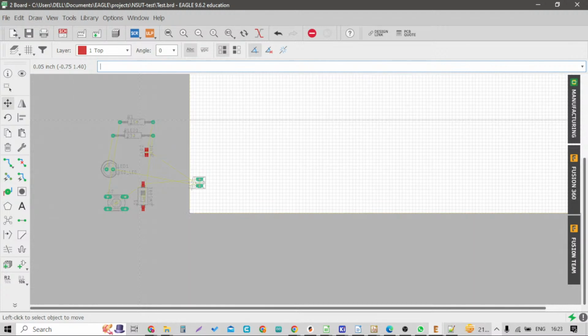So here in this design, we will be actually using or placing the connector on any of the edge, and we will be taking the help of the schematic also to make the placement of the components. But there will be some critical rules that will apply and that we should adhere.